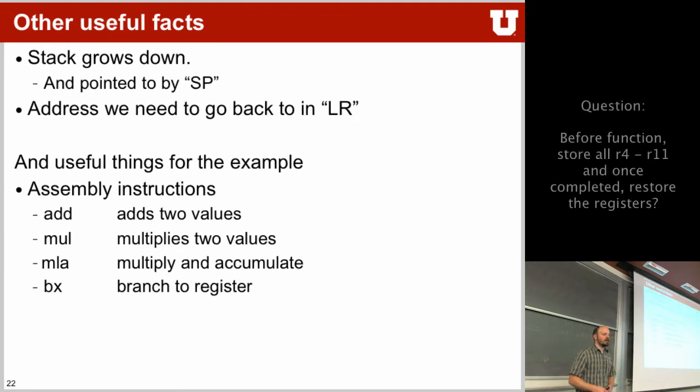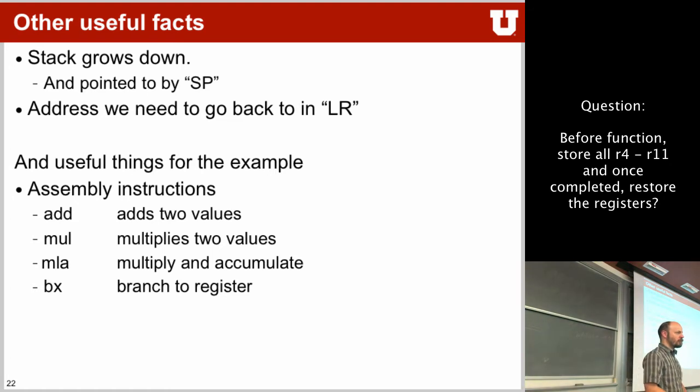Yes? Just to make sure I understand right, before we do any function processing, we will store all the contents of the registers R4 to R11 on the stack, save them, process the function, and then restore them. Correct. Exactly. We will have a couple of examples on how to do that, actually.